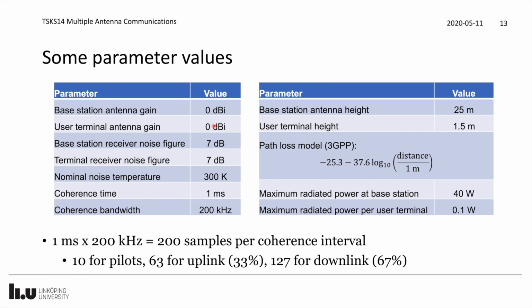When we are computing the noise variance, we need to consider the temperature. That is giving us the ideal noise variance, and then you need to add something called a noise figure to that number, because that is describing the noise amplification that is going on inside of the receiver as compared to just the fundamental thermal noise that will exist.